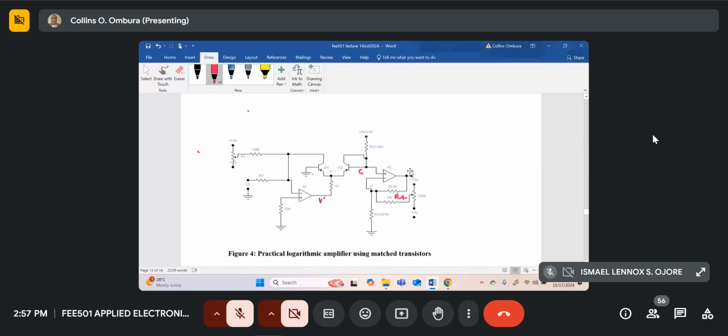So to analyze this circuit, I'll consider an arbitrary voltage V over here, just to help with my computation. The null offsetting circuit does not come into play because we use high resistance. It's just for balancing, making sure that when there's no signal at the inputs of the two op-amps, the output is 0.